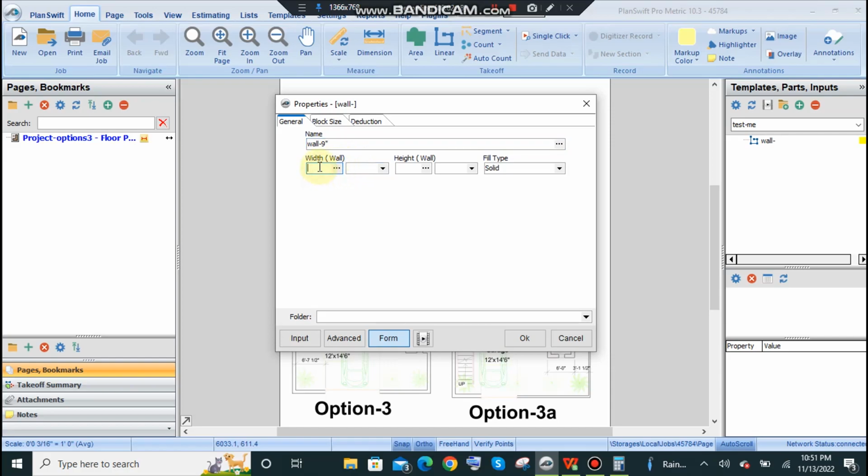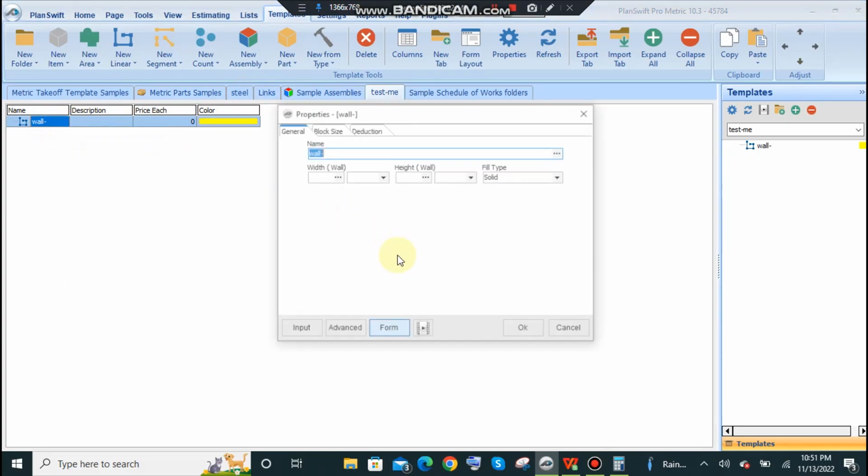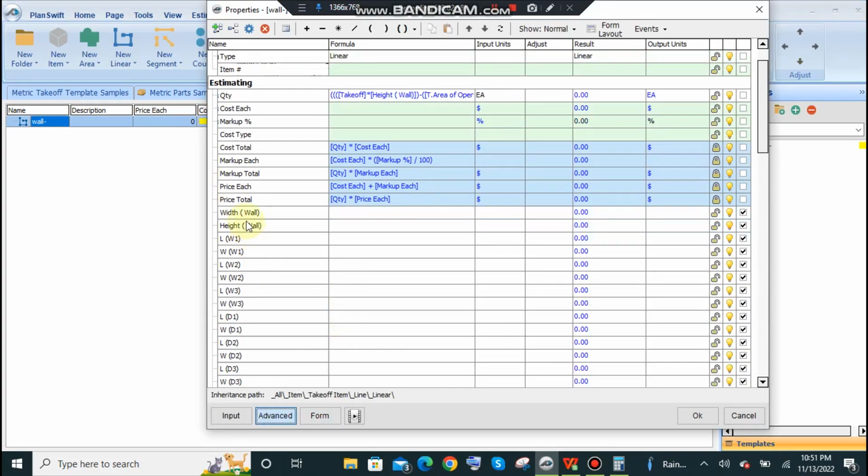So, the width of wall, let's suppose, is 0.5, but the unit is not there. Now this is what I am talking about: first of all you have to tell the software the preferable units. It will give you the preferable units which are already there. You need not always put them one by one. This is a time taking process. So again go back and then set our units, which I must save. Width of wall unit should be in feet, preferable units. You can change it, but it will save you a lot of time, one by one.